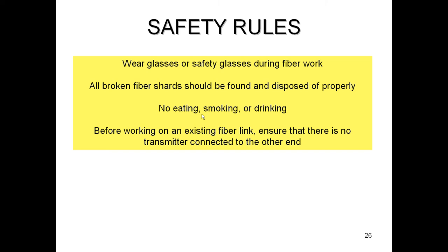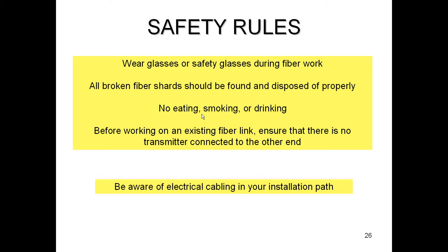So therefore, you want to make sure that on the transmit, if you're going to look at a connector in a microscope in particular, this is where the danger is. When you look at a connector with a microscope, if the laser light's coming through, the microscope is going to amplify it. If it's a 100 power scope, it's going to amplify the light energy 100 times. You're not going to go blind, trust me, because I've done it myself, and you'll know that you shouldn't be looking at it because you go, I don't want to look at that again. Just make sure that before you inspect the connector end, there's no transmitter connected to the other end.